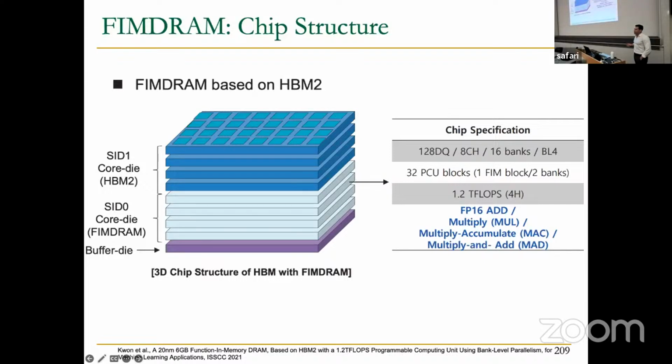It's a little bit different from what I mentioned with the HMC-like design, where we would put the computation in the logic die. What Samsung does is a little bit different, and I guess because they are a memory manufacturer, they can do that. They take out some of the memory dies that are originally in HBM2 chips, and replace those memory dies with compute dies. So basically what you have is some regular memory dies together with some compute dies in the same chip.